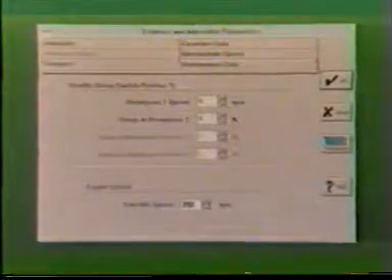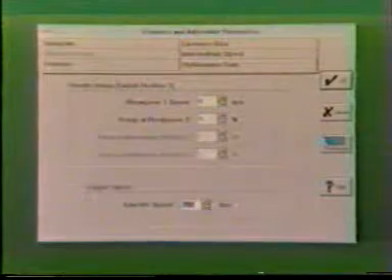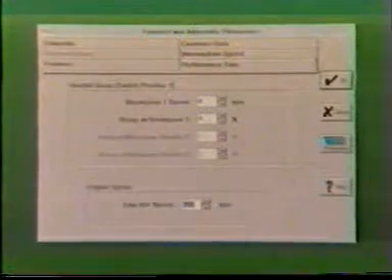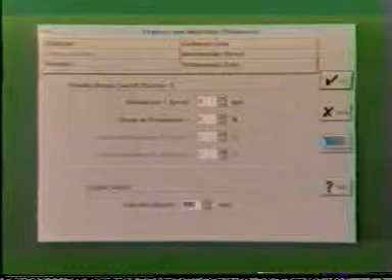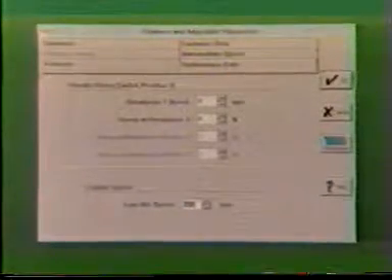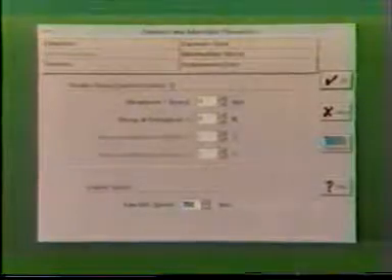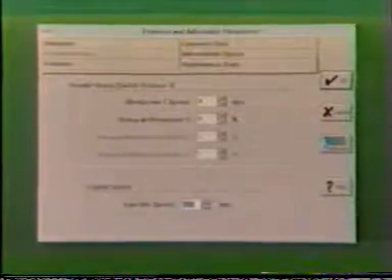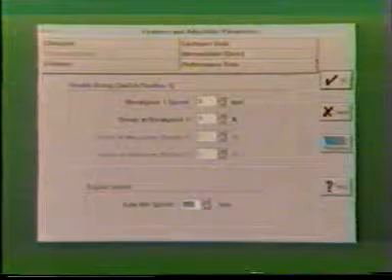The automotive governor would be selected from the Features screen in the Features and Adjustable Parameters function of Insight. In the Performance Data screen, the parameters shown can be set for the automotive governor. Breakpoint 1 speed is the RPM at which the fuel curve transitions to high idle droop. Droop at breakpoint 1 is the percentage droop setting at this RPM.